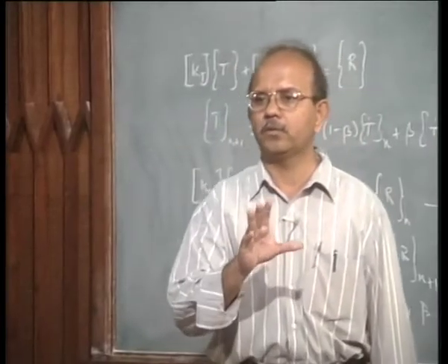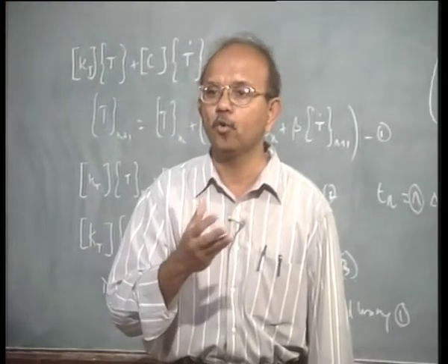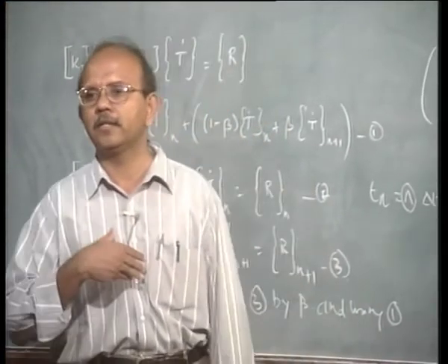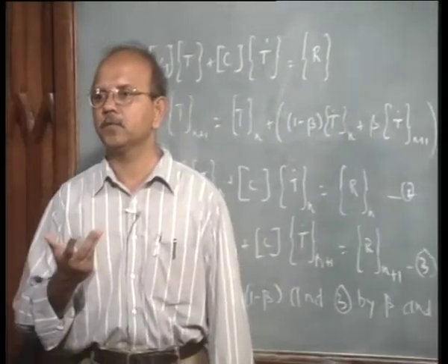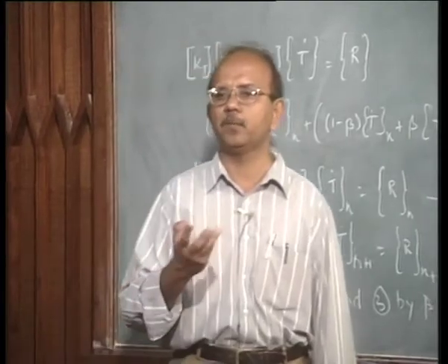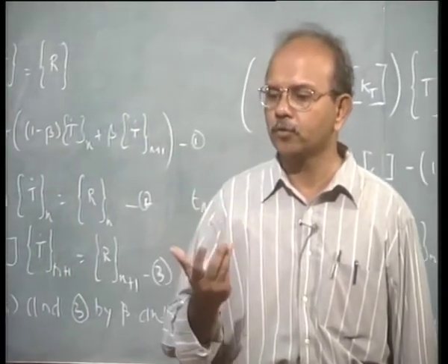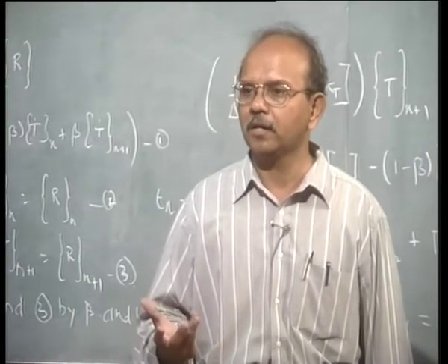So right now it is important to understand physically that you have chosen a shell element. You know why? Because we are dealing with a pipe. One of the best elements that you can see immediately looking at the configuration geometry and looking at how it is going to behave, you automatically say that you choose a shell element.